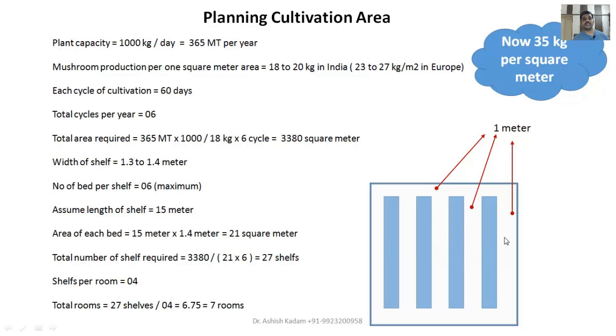And we have understood that we have to develop the microclimate. We discussed in great detail in the last video, number 3, that microclimate is very important, and that microclimate has to be uniform across all shelves, across the entire room. If there is no proper air distribution, or no uniform air velocity, or no uniform CO2 level or oxygen level, then you will get uneven production.